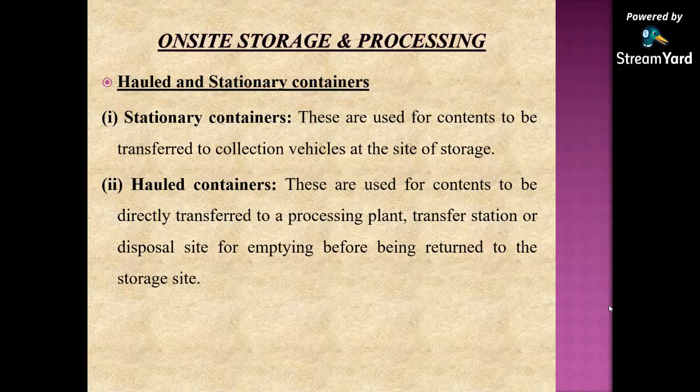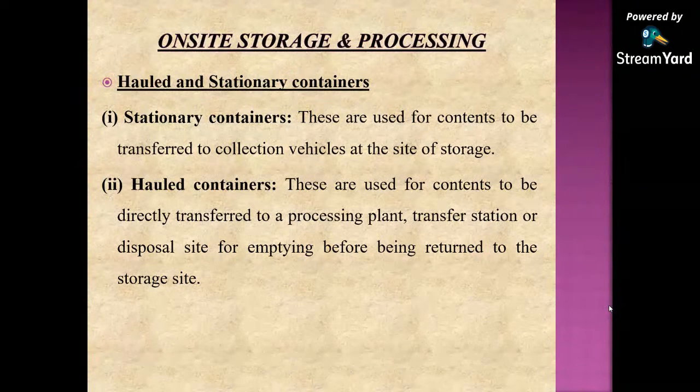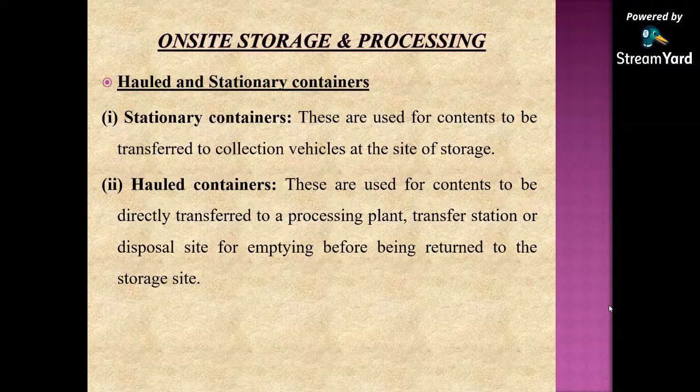The container body must be strong enough to resist and discourage stray animals and scavengers, as well as withstand rough handling by the collection crew and mechanical loading equipment. The container should be provided with a lifting bar compatible with the hoisting mechanism of the vehicle. The material of the container should be light, recyclable, easily molded, and the surface must be smooth and resistant to corrosion.